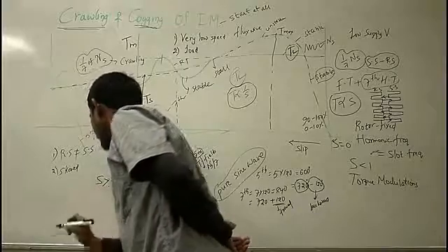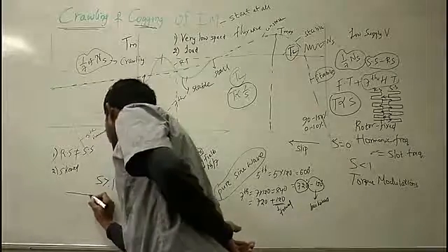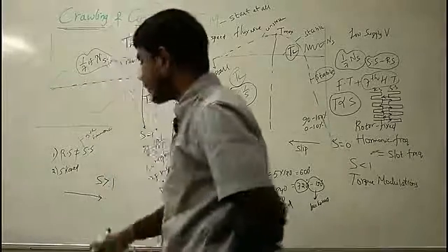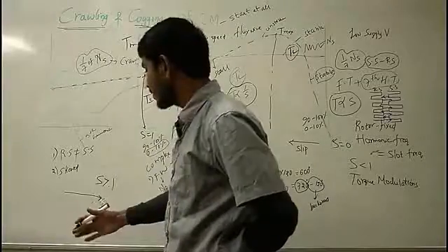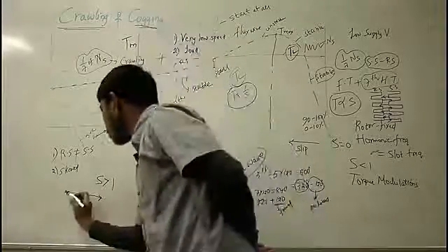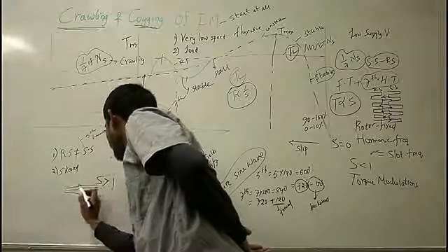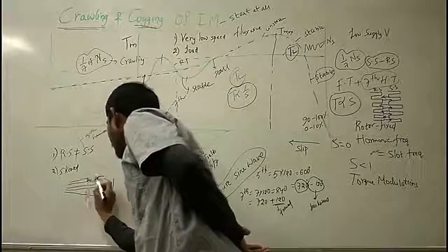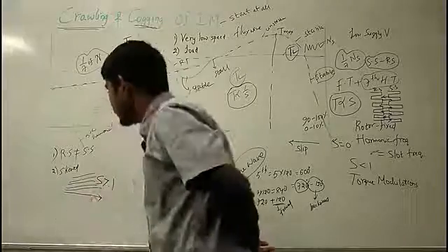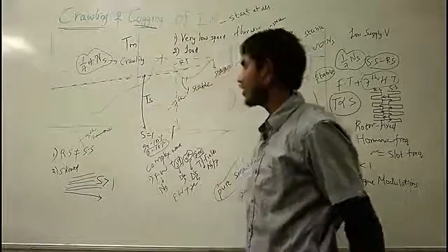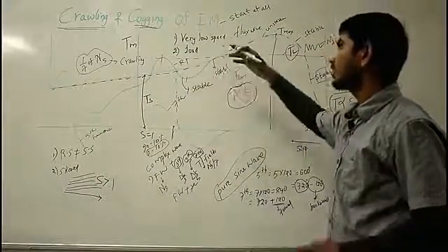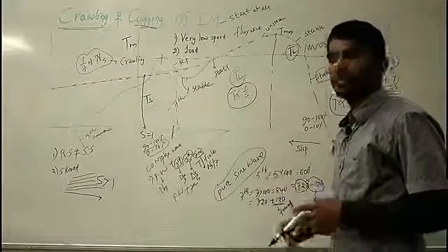If I say this is the axis of rotation, they should be neither parallel nor perpendicular to this axis of rotation, but they should be arranged in a slanted manner like this. And this prevents the magnetic teeth locking, and this automatically prevents the cogging effect of your induction motor.